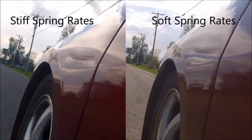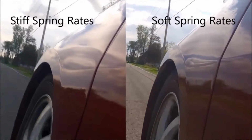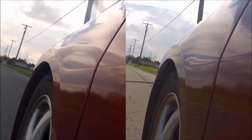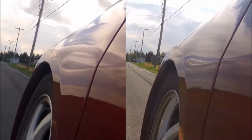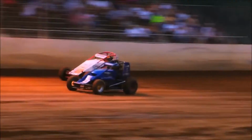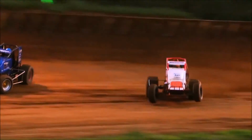As you can see in the video, the vehicle with stiff springs does not adjust as much over bumps, providing poor ride comfort. The vehicle with softer springs, however, does adjust over bumps. However, if this vehicle's springs are too soft, it will adjust too much over bumps, providing poor ride comfort as well. When setting up a race car, you select springs to add or subtract weight and essentially steering or drive force to get the right amount of oversteer or understeer.